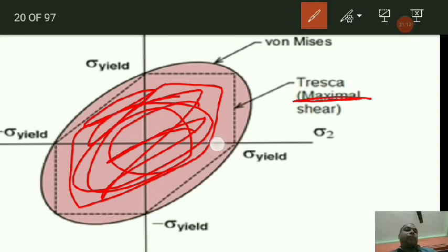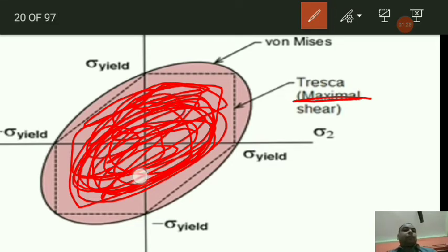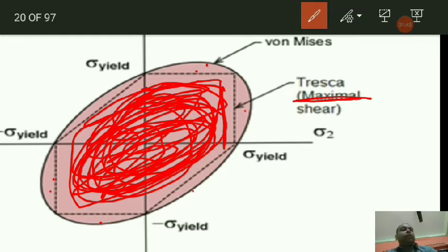If your normal stresses lie inside this region of this polygon, then you have a safe design for your ductile material, or working on the material is safe. But if the stress developed is outside this particular polygon, say this one, or this one, or this one, then it is not safe, because your material will develop cracks and eventually it will break.